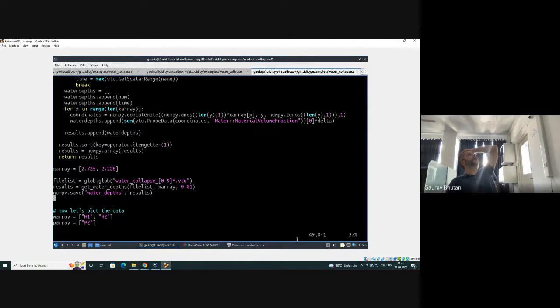Maybe it's already... It is calculating here. I can see that. It's doing something to the volume fraction and multiplying it by delta. We'll have to understand a bit further. Maybe it's using a different method. So either you can find it wherever the volume fraction is half, or you can find it through change. Wherever there's an interface, there's a strong change in alpha. So rather than looking at the value of alpha, you look at the gradient, the change in alpha. That could also have been used.